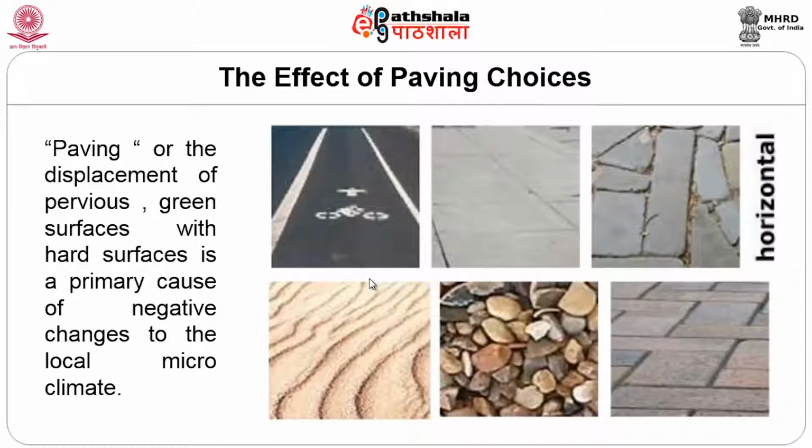But what we end up doing is, once we design the main purpose of a building, to make maintenance easier, to ensure that there is no waterlogging around the building, we end up putting up impervious surfaces like this around the building and making sure that there is no water retention or water entering the water table anywhere.